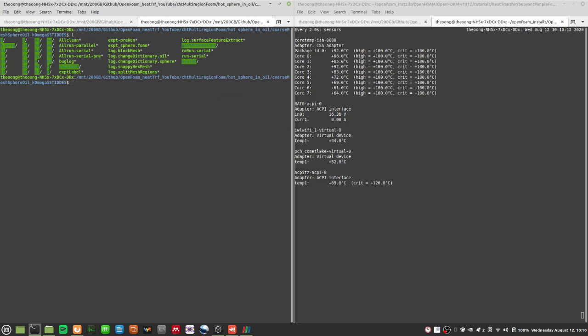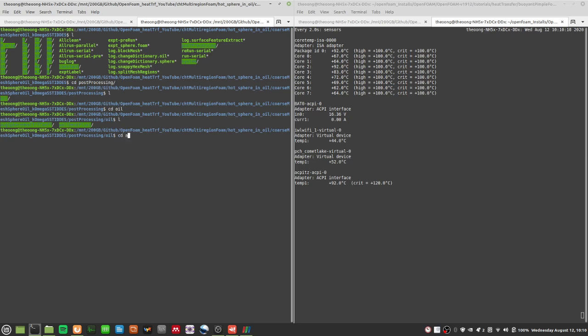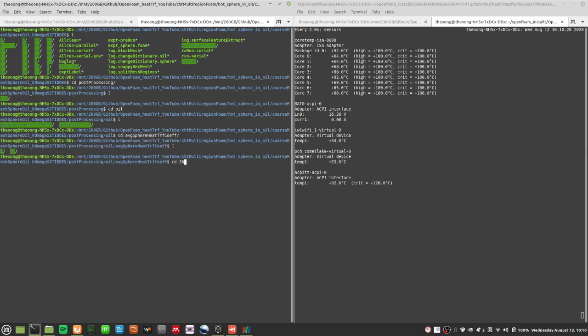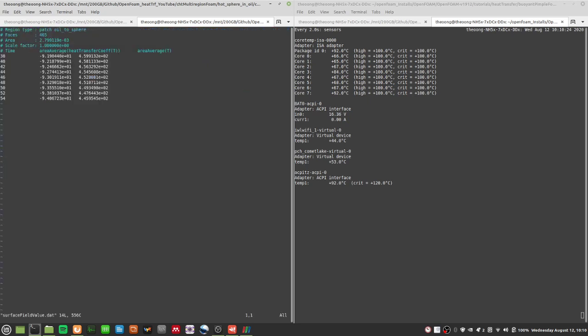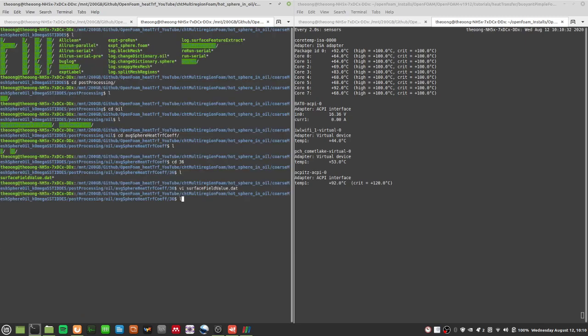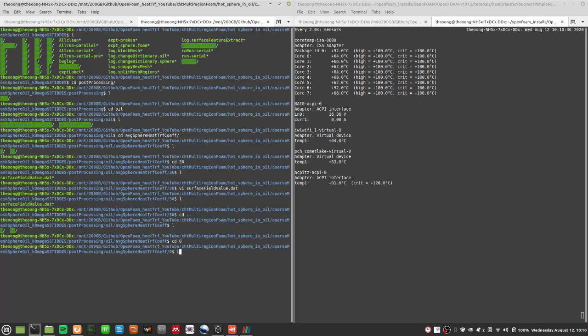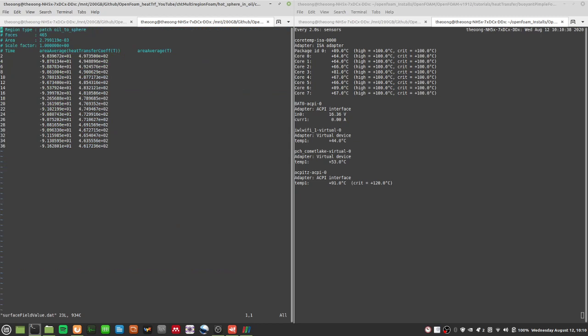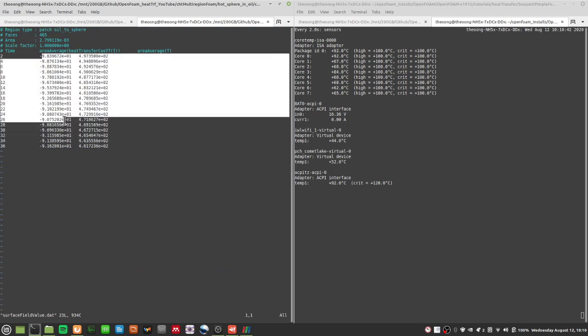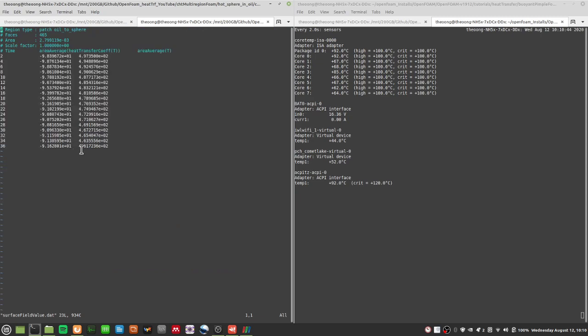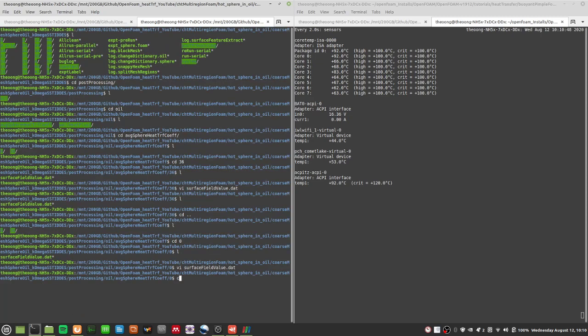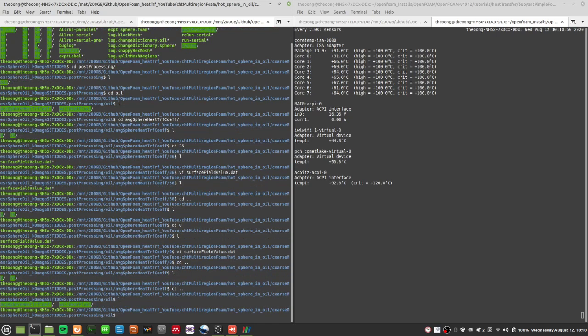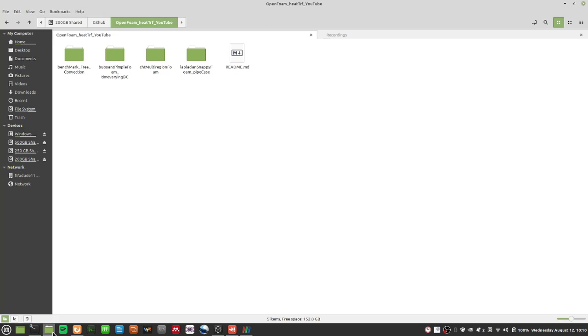Alright, so let's take a look at the post-processing, and we can see the average heat transfer coefficient, if there's anything over there. Okay, I do have some data over here. You have an average temperature and some heat transfer coefficient. Again we have a heat transfer coefficient of about 90 something, 100 and something, give or take. Now how does that actually compare?